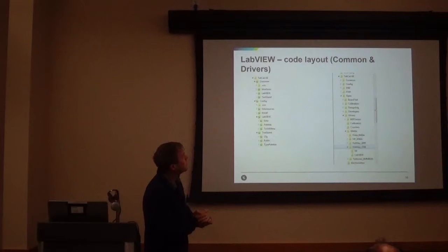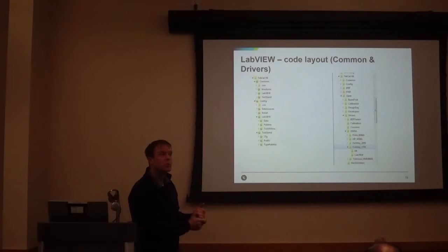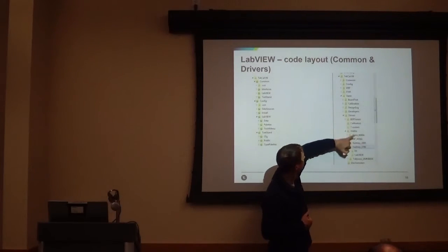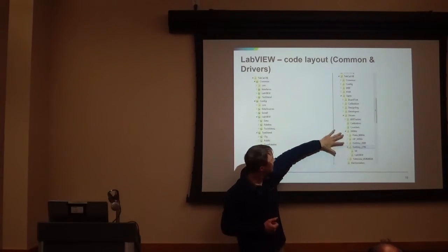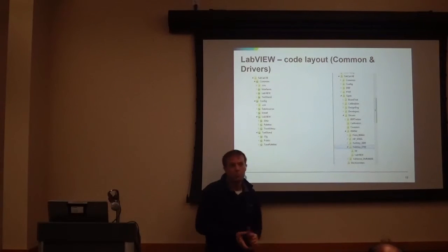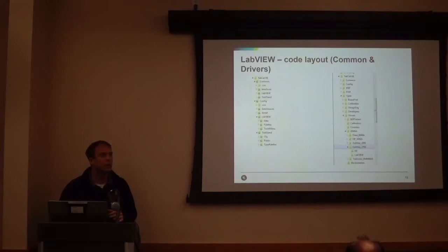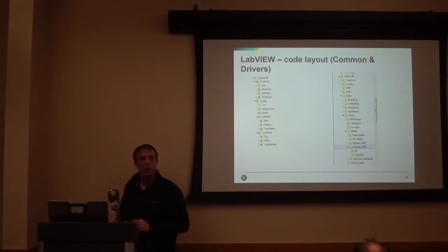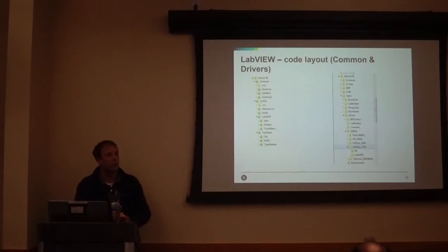We also end up having a standardized place where we're going to put all the drivers on disk. Instead of having to go to each station and install individual drivers, they get deployed by our code deployment process, where we have a drivers folder that has a bunch of categories of instruments, and all the DMMs are organized under there. So hopefully people get good reuse of at least the driver modules. And yes, we do have multiple different flavors of drivers depending on whether people are running IVI or just a straight LabVIEW driver, or the DLL for CVI code or something else.